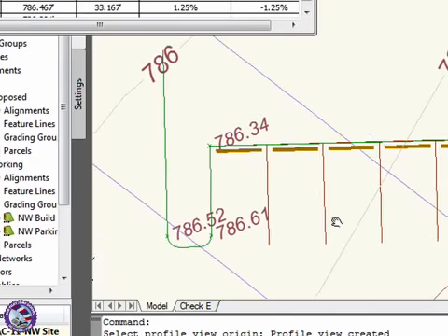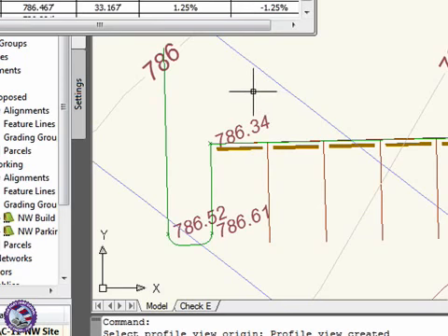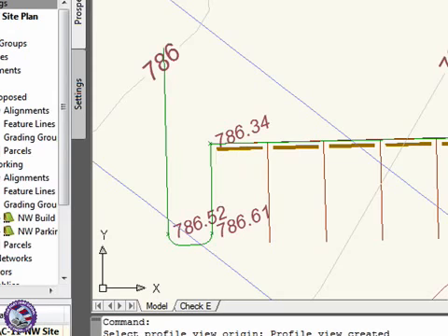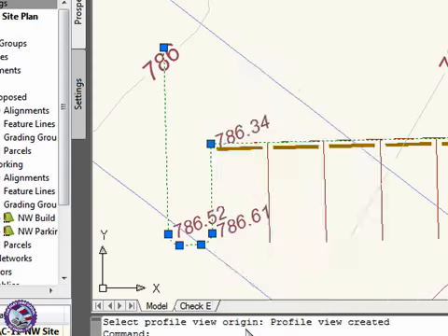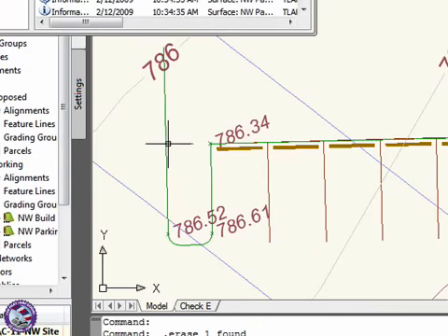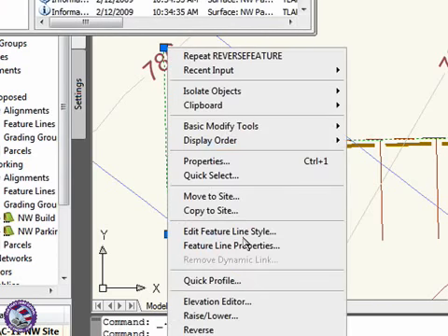We can actually visually edit what's going on in here by changing grade heads. If you pick, let's see where it started. Right, so it would also be possible to, perhaps I would like to reverse this, and since it's a feature line, I could do that. So I'm going to close out of this for a sec and say, I'd really like to start out from the street, so I'd like to reverse that feature line. And now when I go back to the editor,